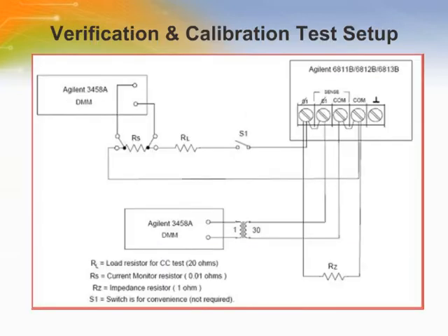This page shows the setup for the tests. Care has to be taken to use load leads of sufficient wire gauge to carry the full output current. When performing the verification tests with the GPIB controller, you may have to consider the relatively slow settling times and slew rates of the AC source as compared to computer and system voltmeters. Suitable wait statements can be inserted into the test program to give the AC source time to respond to the test commands.